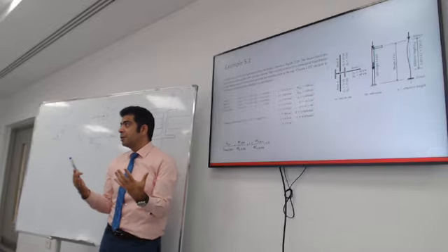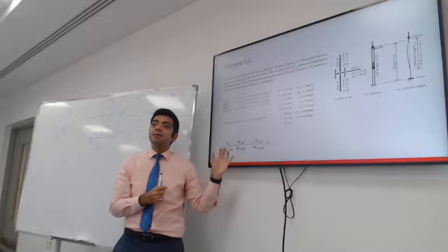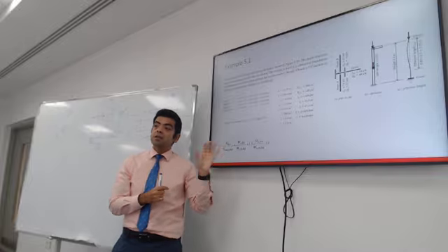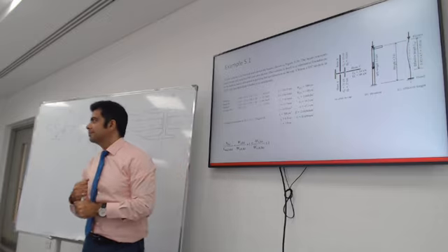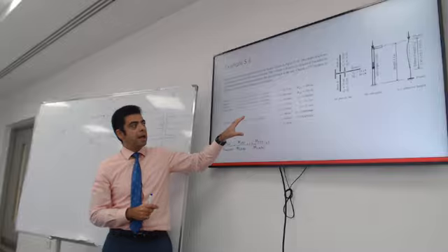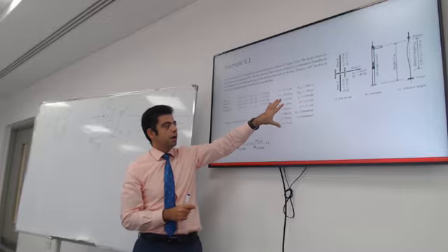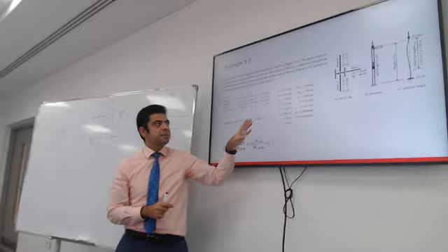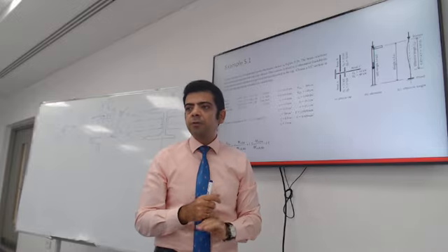It's too much stress for that section. So what happens if you realize that the stress on this section is bigger than 1? What would you do? Choose a bigger one. Yes, you will have to choose a bigger section and make sure that all the properties, when you plug them into the equations, are safe enough to take the load.